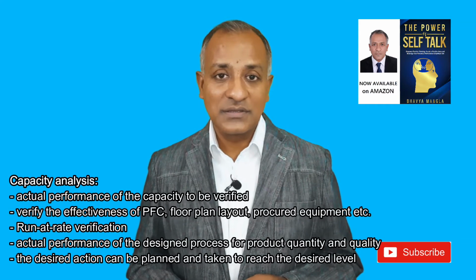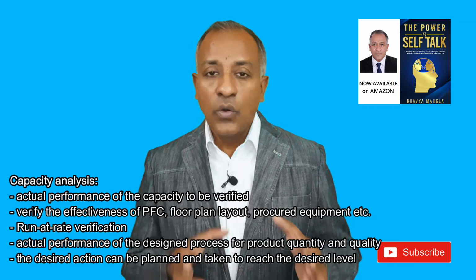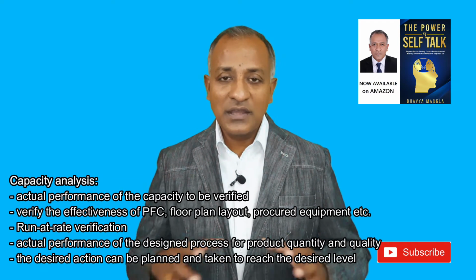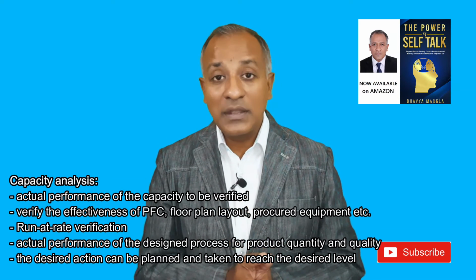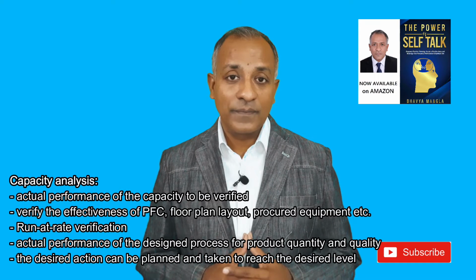Then the next output is capacity analysis. Now, initially there are certain targets that are set for what the production volume will be every day, every week, and every month. So based on this production trial lot, the run rate study gives an idea whether we will be able to meet the customer requirement in the long term or not. And if not, what needs to be done with respect to that.